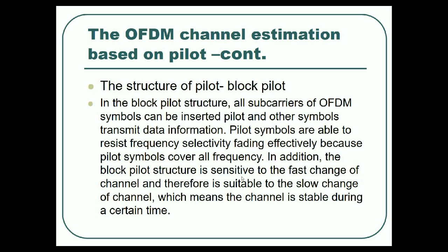Pilot symbols are able to resist frequency selective fading effectively because pilot symbols cover all frequencies. Also, the block pilot structure is sensitive to fast changes of the channel and therefore is suitable for slow changes of the channel, which means the channel is stable during a certain time.